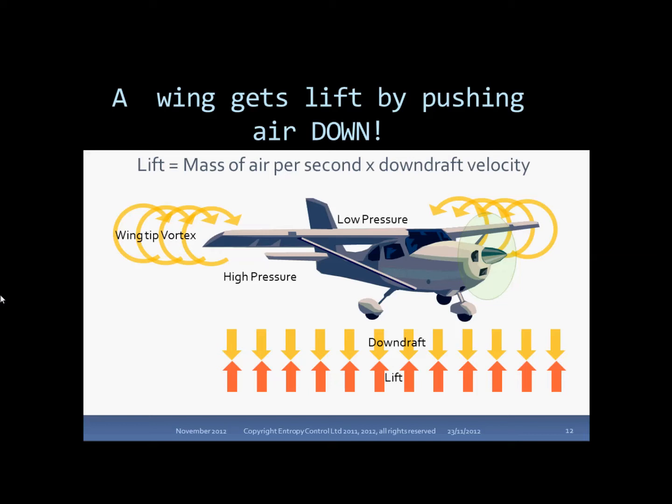You can think of a fixed wing as being part of a rotor blade going round in a very big circle. The downdraft mechanism for a fixed wing is that high pressure underneath the wing and low pressure above produces a wingtip vortex at each tip, and the two of them induce a downdraft below and behind the aircraft. And most of the strangeness in behavior of aircraft, as opposed to other vehicles, can be traced straight back to the existence and behavior of that downdraft.